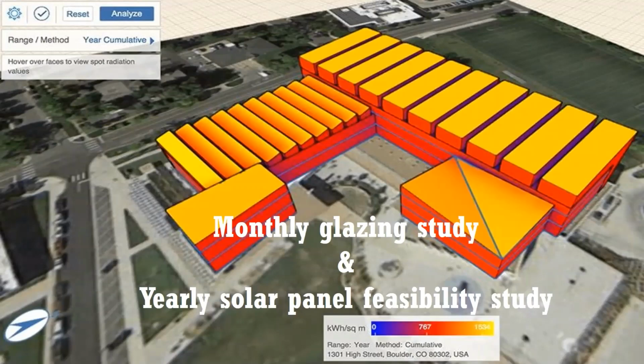I'll be getting that yearly sun exposure value, and it will be provided with a graph, showing the EUI. I'll be getting the energy retained. What will be the value of energy retained? It will be represented in kilowatt hour per square meter over a surface. So here I'll be getting an idea. If I provide my solar panels in this area, I'll be getting maximum return as conventional energy.